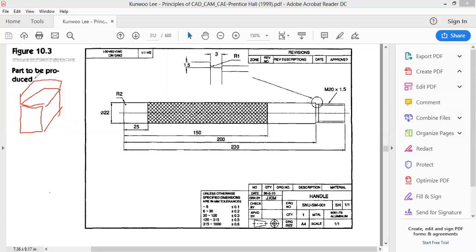And then it has to be assembled, where this engine head and engine body are assembled by nuts and bolts, where particular sequencing is going to be done. Which nut out of these should be inserted first, and by how much it should be tightened.